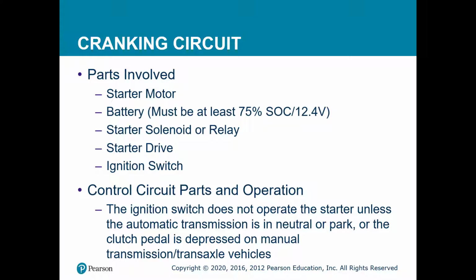There is the starter drive, which contains the pinion gear that will engage with the flywheel ring gear. And then we have, finally, the ignition switch. That's the part you're engaging with, so your fingertips are touching. So that's the key in the ignition, or it could be your push button, or it could be remotely. However it is, that's the part that you engage with.